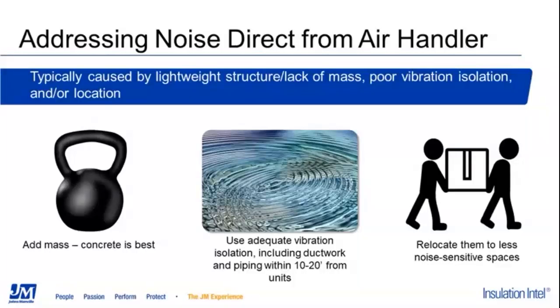This can also be beneficial for reducing vibration issues. In all instances, it's critical to be using proper vibration isolation. The ASHRAE Handbook, Chapter 48, has an entire section dedicated to selecting the appropriate mounts. A lot of new air handlers do have internal isolation, and it touches upon that, but it mostly speaks about exterior isolation for the entire unit itself.